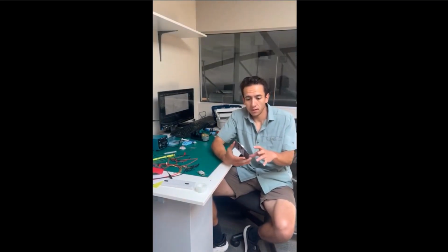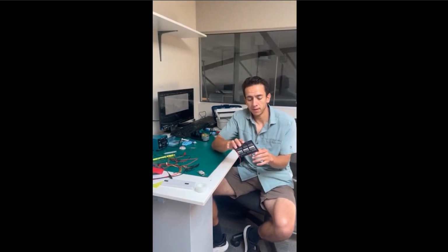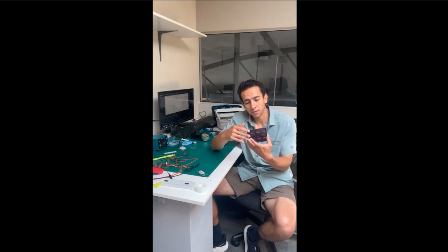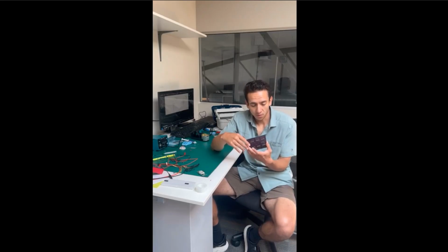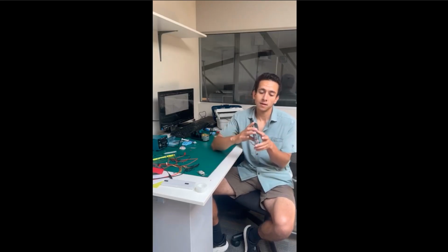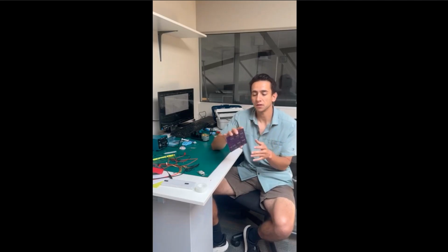So yesterday I turned it on, and as you could tell, it did not work. So today's a new day, and I looked at the board, and it turns out U4, my LED driver, was connected backwards. So hopefully this was the only issue. Mistakes happen. And so I'm gonna flip the chip, and hopefully the board will work.